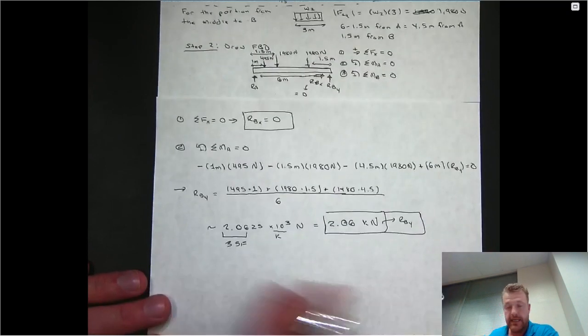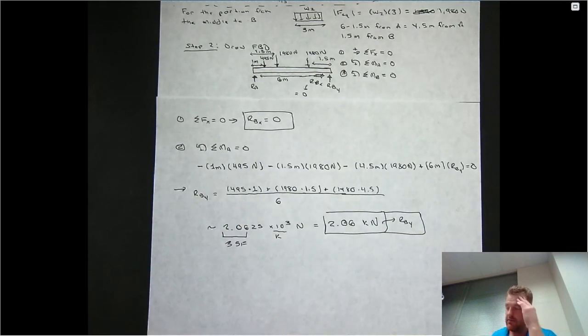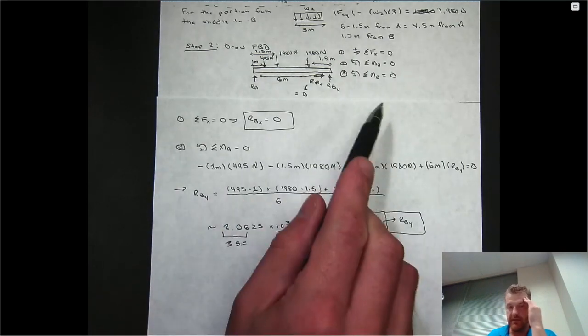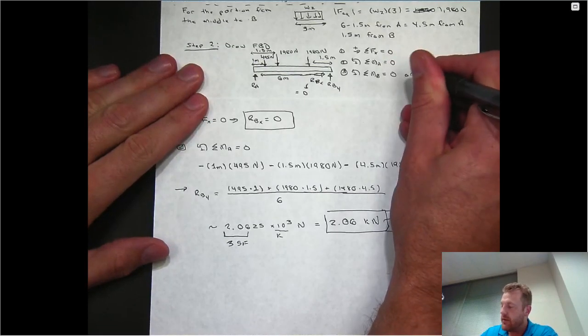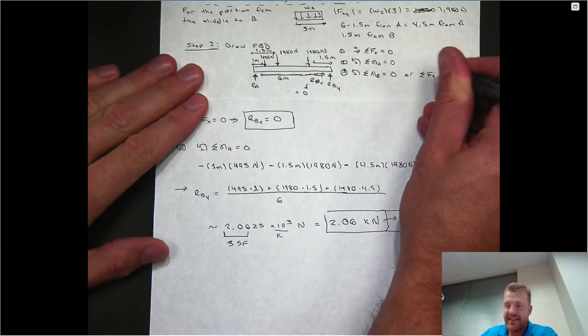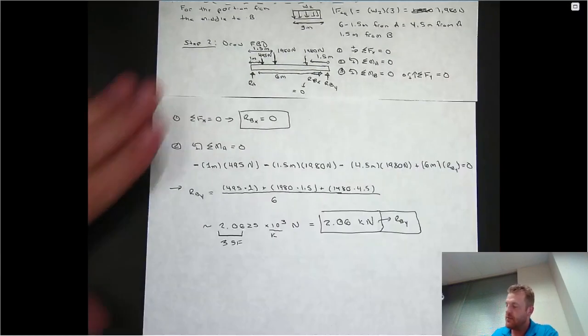So how will we get the expression for the vertical reaction at point A? Well, there are two different ways that you can do this now. You could sum all moments about point B, and you might want to practice doing that. Or, if you only want to write one moment equation, you can just sum all forces in the vertical direction.